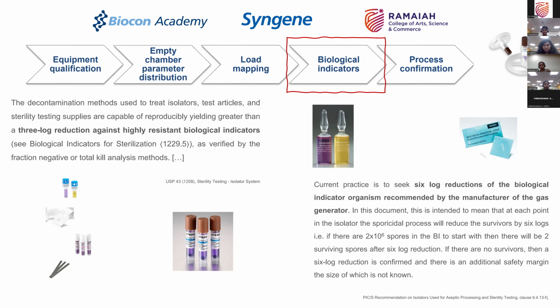In case of VHP and autoclave, you will do an empty chamber cycle. In case of gamma irradiation, you can't do an empty chamber cycle, so you will do it with a minimal load or a load mapping. You will always do a load mapping for a new facility or a new autoclave.